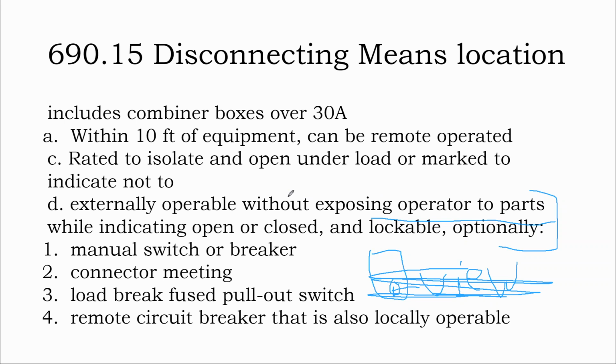That knife switch disconnect, where up is on and down is open, that you can just pull up to the side of the house and look at that knife switch to see if it's open or closed. That's an indicating, closed, lockable, operable switch. A knife switch is not the only switch that is allowed by code to be this disconnecting means.